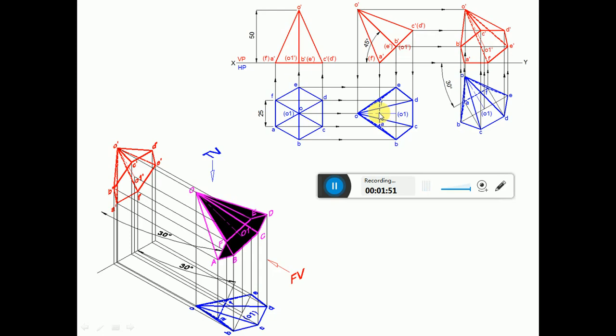Then by using the compass, you measure the distance from this point to O. From this point, you mark the distance here, O. Then you measure the distance from O to O1, and since you have already drawn this perpendicular line, from O you mark that distance here to get this point O1. Once we get this O1, which is a center line, then from O1 by using the protractor you measure an angle of 90 degrees with respect to that O1 line and then draw a perpendicular line to O1.